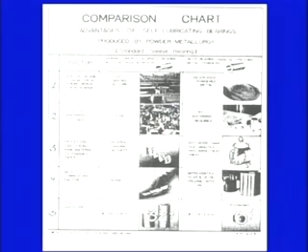Now, this is one comparison chart which shows an ordinary bronze or brass bearing and a bearing made by powder metallurgy. The first point is the cost of the blank basic piece from which the bearing has to be made. For the bronze bearing, it is a costly casting or tube.